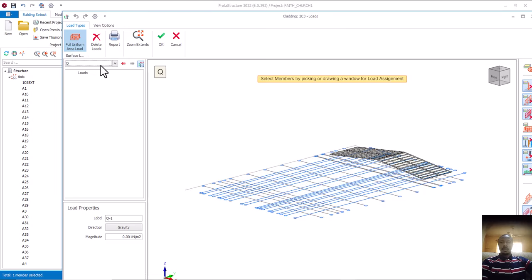Looking at our live load according to Eurocode 1, EN 1991, section 1, subsection 1, it says that the characteristic imposed load, that is our Qk, is between 0.5 to 0.6 kilonewton per meter square. You know that when you are using Eurocode, it's with a meter square. So since the Eurocode has already helped us, our characteristic imposed load, which is the Qk, is between 0.5 to 0.6 kilonewton per meter square. Now, it depends on the slope.